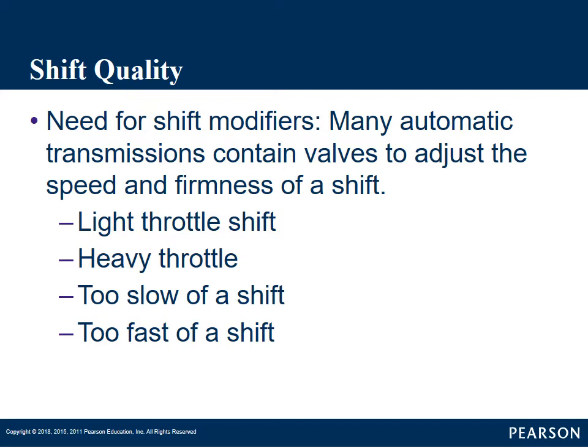The speed of a shift is from when it first applies pressure to when the clutch pack completely engages. Think of it, if you've driven a manual transmission, from when you start letting out on the clutch until you've let that clutch all the way up.